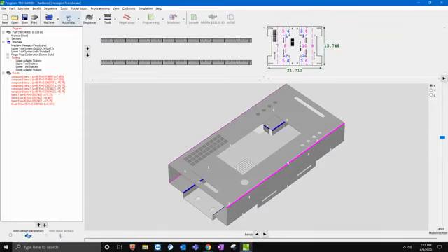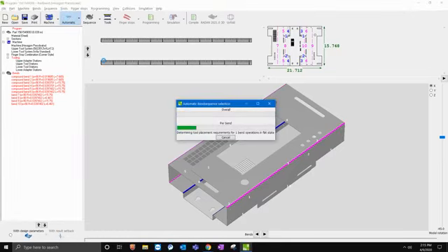So I'm going to sit here and select automatic. It's going to look at this and determine the tool placements, the finger stop placements, what kind of tools it's going to use, okay? Because in Radbend, it's going to do tool optimization. It's going to do automatic finger stops, automatic sequencing. We want everything to be quick and easy, right?